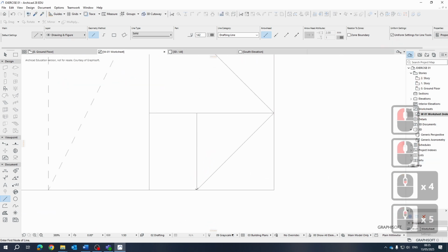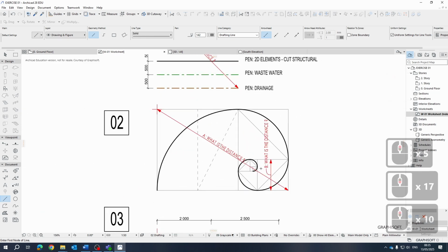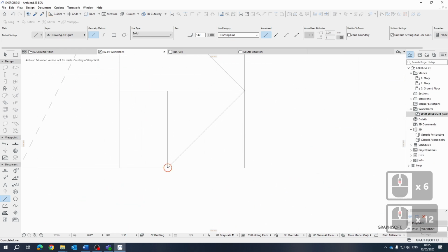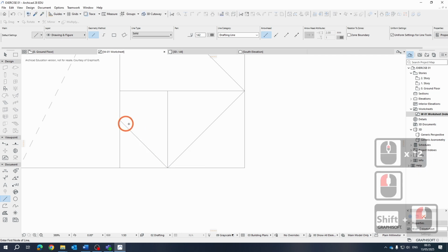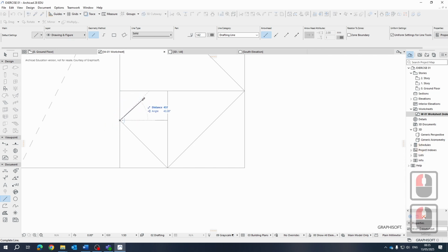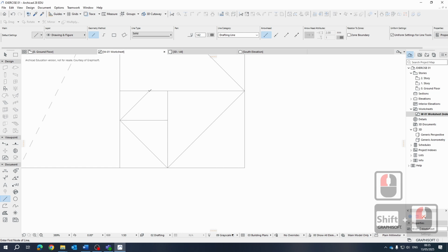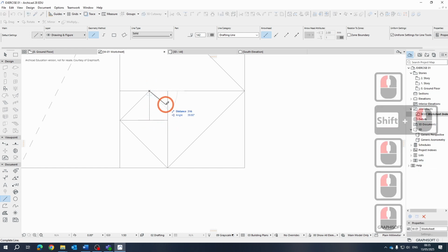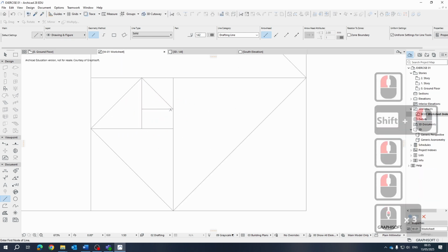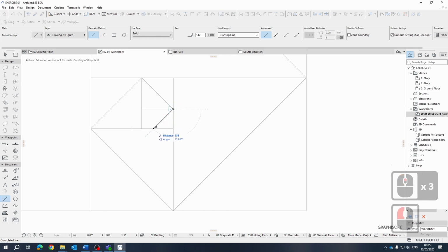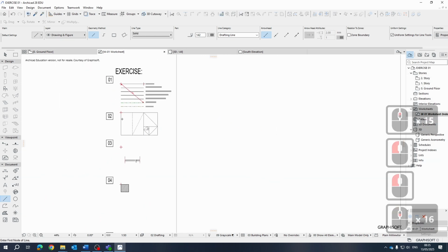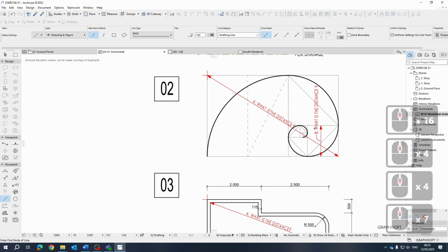Okay. So we're going to keep repeating this process until I've achieved this shape. We need to do it 4 more times. So we're going to draw a bit of line work, 135 degrees. Draw a bit of line work. Keep going. 45 degrees, snap, go down. Snap, keep going. Okay, we need one more bit of line work. And we'll draw one more bit of line work up. Okay, so this is a good exercise on how to use the different tools and how to snap and intersect lines and how to draw accurately.